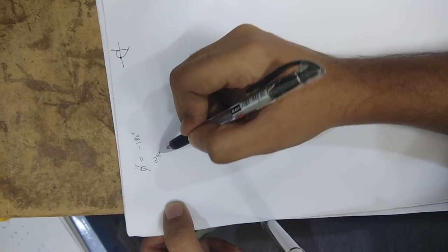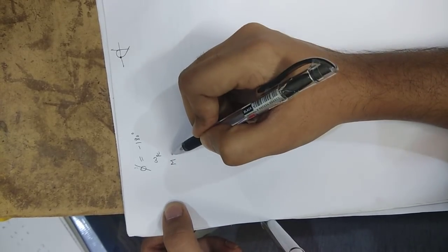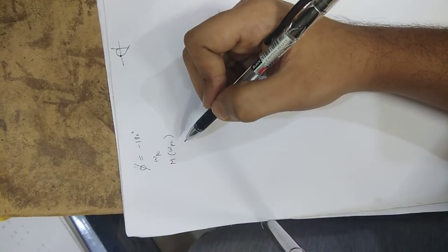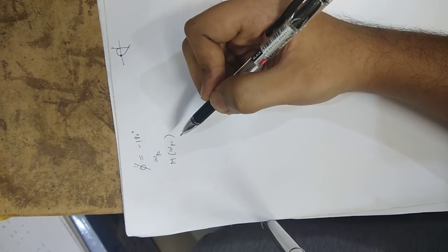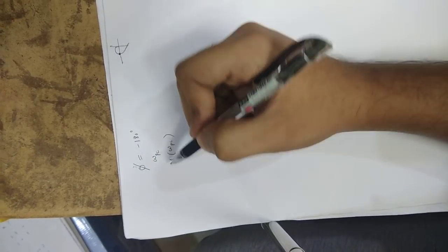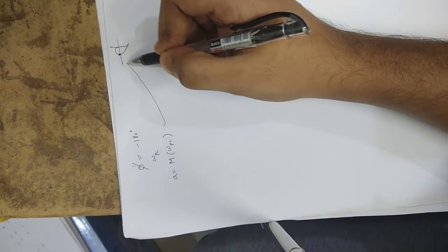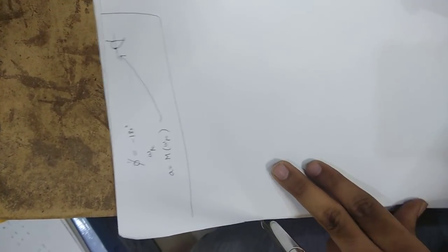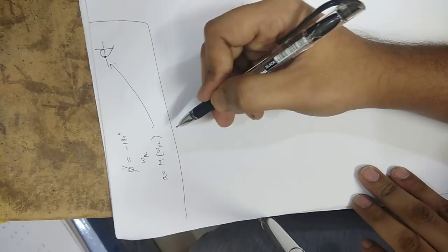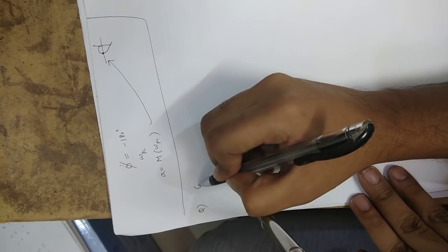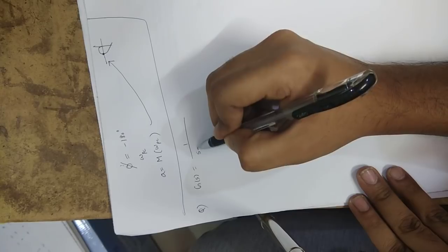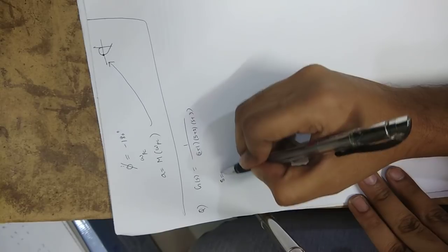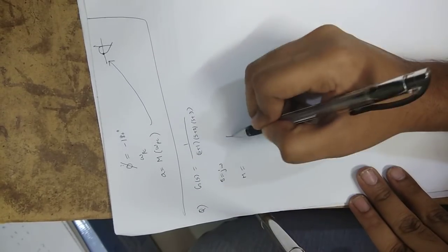And now substitute this omega in the magnitude. That means the OLTF magnitude at omega pc. In this magnitude expression, substitute omega pc and you will get some value. That value is A, and that A is this intersection point. So now we will get this case in the following problem. G(s) equals 1 over (s+1)(s+2)(s+3). Put s equals j omega, magnitude 1.